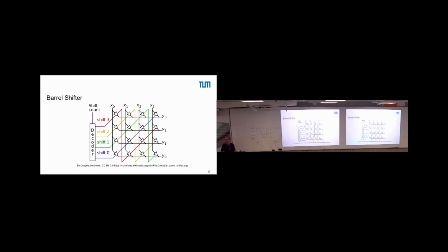So it's just the colored line enables the switches along the colored path. And that's it. The benefit of this one is each of these things is just 2 transistors, plus 2 maybe for the inverter, but you can join them probably. So it's a simple matrix of switches, and you can, in one clock cycle, just go through. The depth is always only one of these things. It's also quick. So that's actually the way to go.